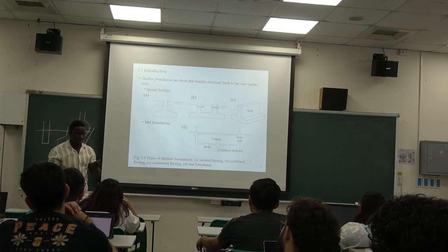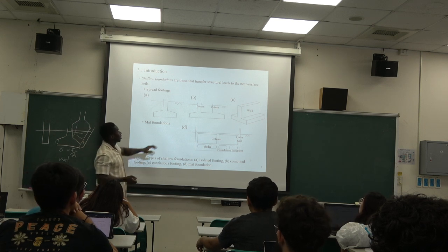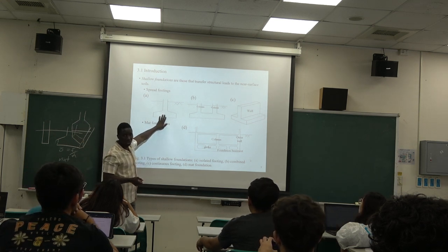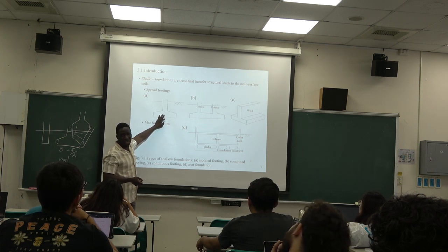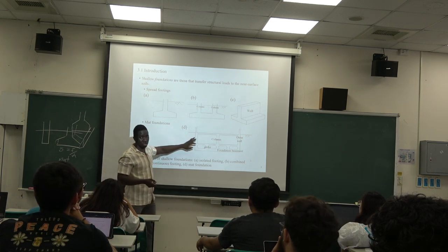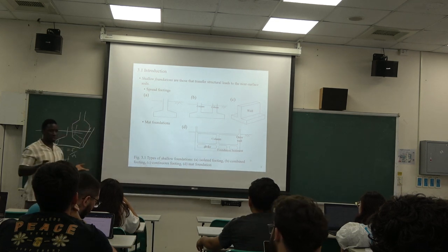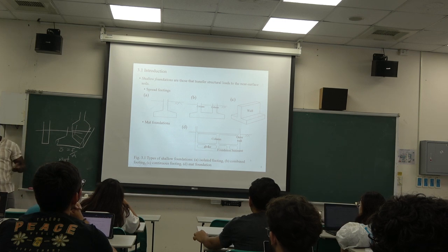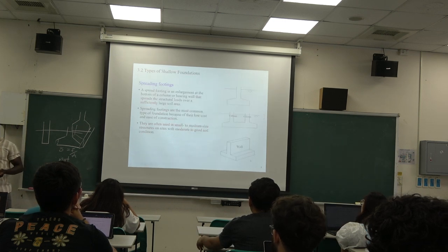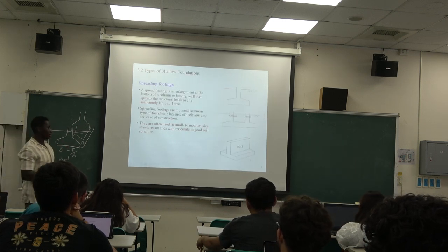The more load the foundation needs to take, the more footings you will need. But if you design the footings and you realize that the number of footings you need is too much, then you will just use a mat foundation instead, because it's more reasonable. I think in the next slide we will see, it will give a much better idea.